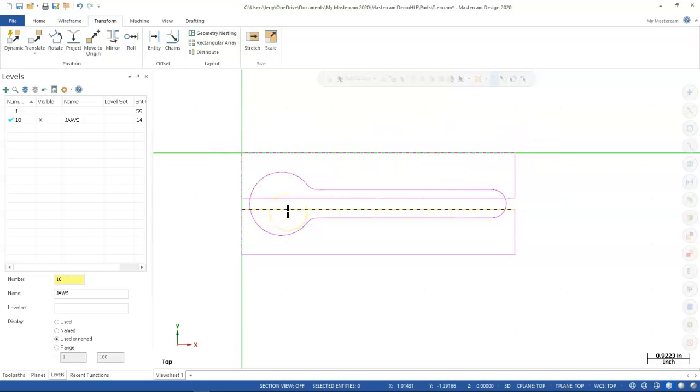If we needed geometry, all right, we're going to do engraving, or we're going to add an additional pocket or something on this side of that wrench, I'm going to be able to do that because I have a known location. Now, as far as picking that location back up, I'm relying on these soft jaws. If these are aluminum and they're short run production, maybe we're running 100 parts, I can trust the aluminum to hold this piece. But after the 100 parts, I'm kind of expecting that aluminum to start to deform. Every time we close it, it's smushing it a little bit. And that accumulation of smush is going to come to a point to where it's not going to be as tight, or it's going to start to drift.